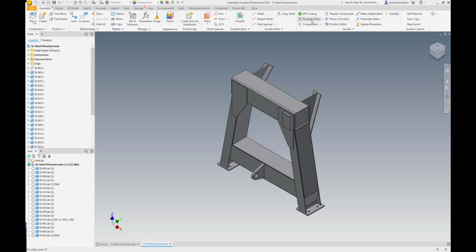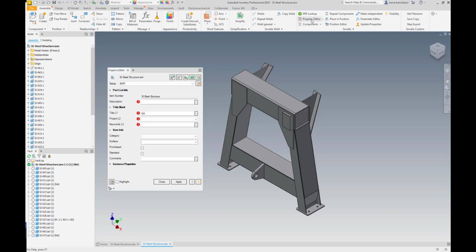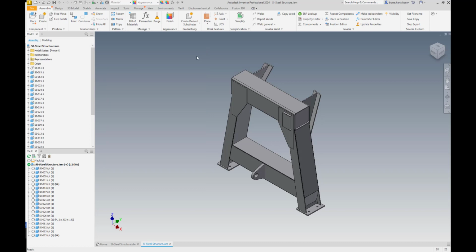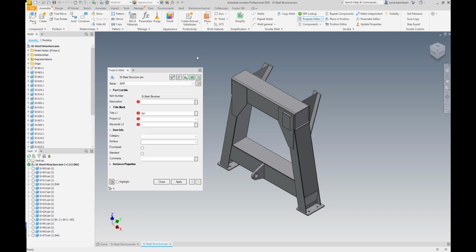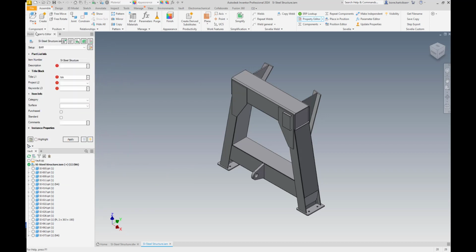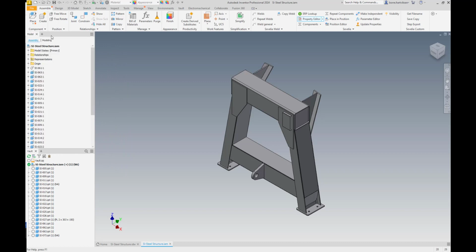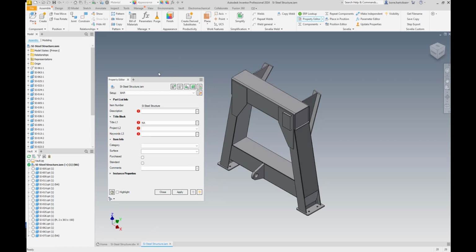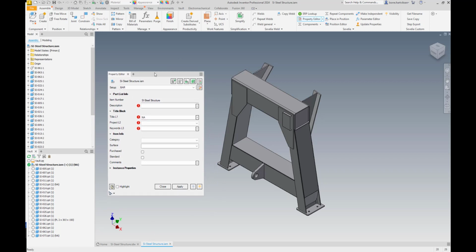The property editor is the base of Sovelia Inventor. And we can start it from the ribbon menu from here, or you can just do like I like to do. I can set Control Q, or you can, in the configuration, set up any combination of letters to pop it. So it can also be docked, as you see, just like any other Inventor dialog box. And so this is just a matter of preferences, how we like to have it.